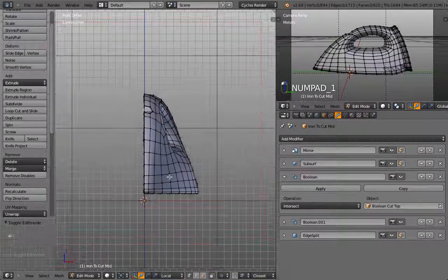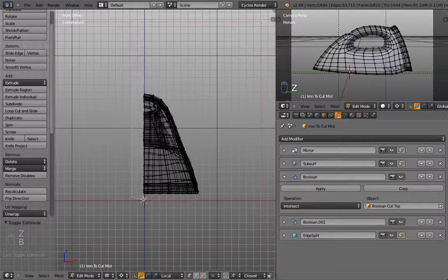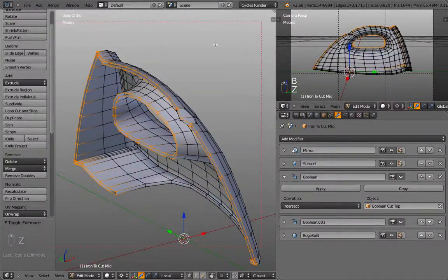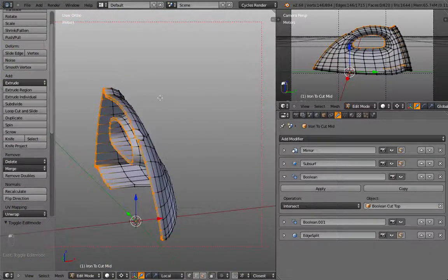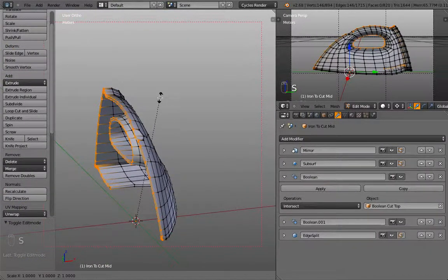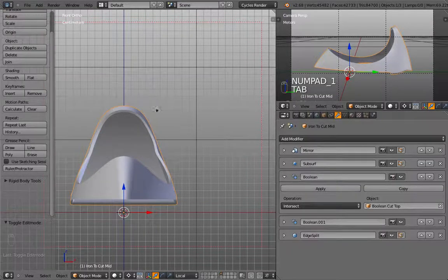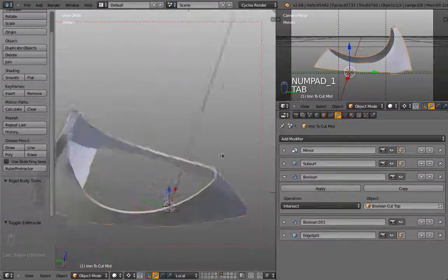So that's the reason why I snapped my 3D cursor to the object center. I set my 3D pivot point to 3D cursor, select all those points that define the cross section, and then simply scale along the x-axis to 0. So now they're all straight. And let's leave edit mode, and voila! You see? Everything works. Perfect.